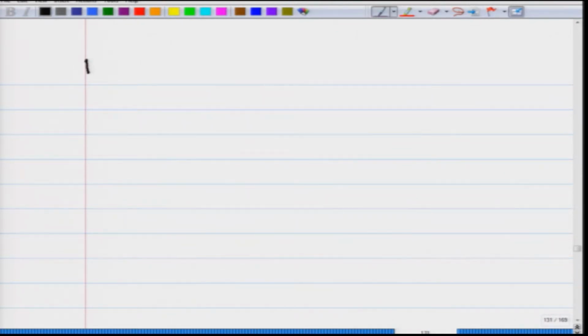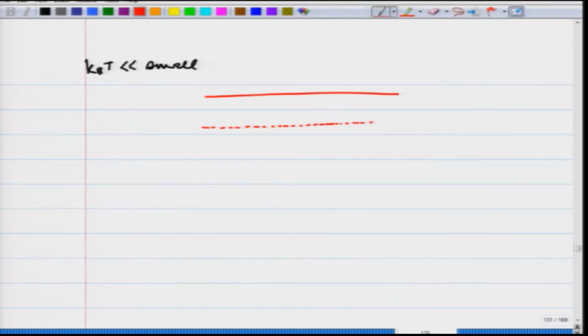When KBT is very small, then here is the conduction band, here is the donor level, mainly carriers are coming from here. So, like we did for intrinsic semiconductors, mainly things are coming from the donor levels, and let us say the concentration of donor levels is ND.